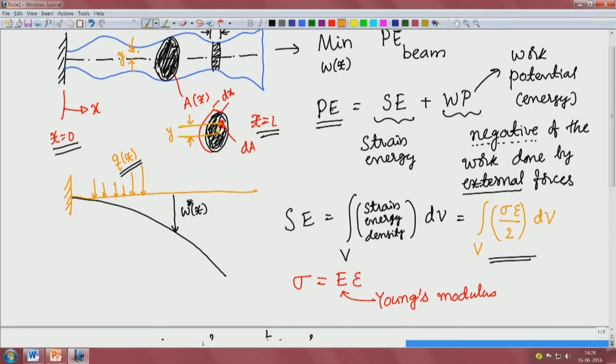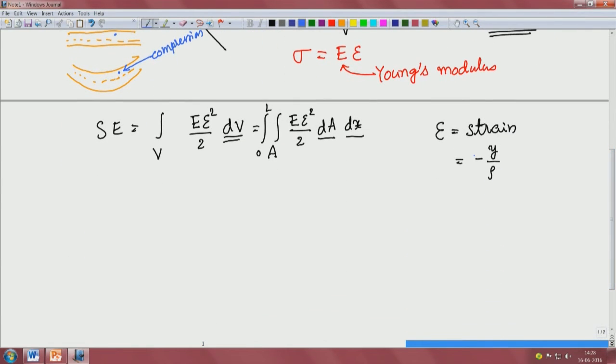As the beam bends, the convention we take for a beam that is straight like this, deforming like this, is considered positive. So, if the neutral axis is the center like this and I take a point above the neutral axis, that would be here, these things will be under compression, and hence strain will be negative, and that is why we have the minus sign over here.